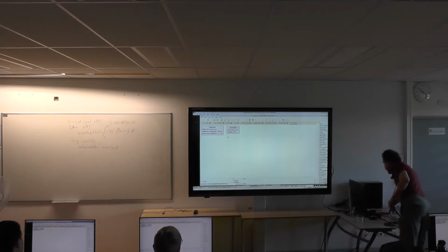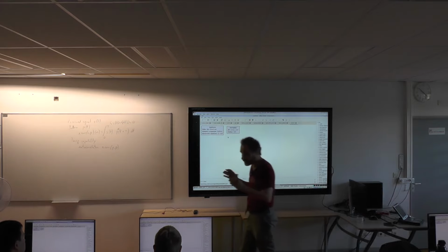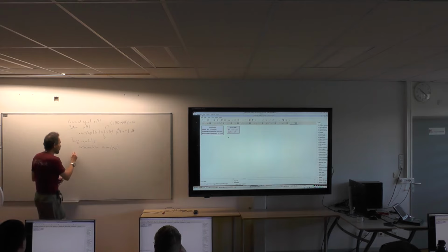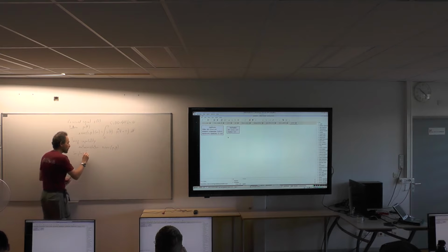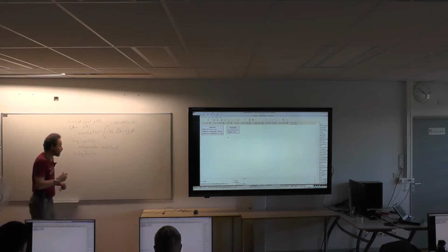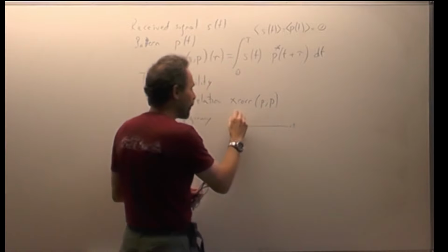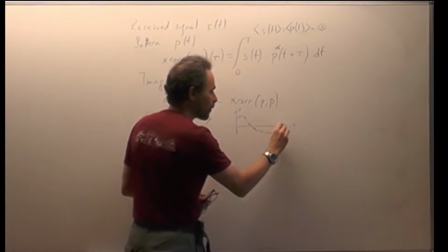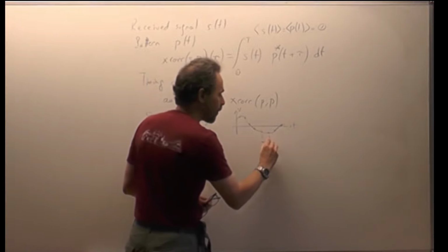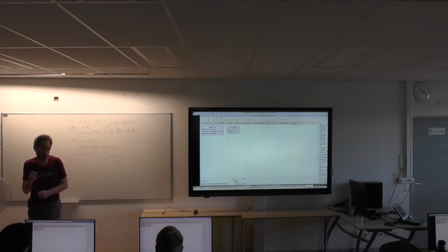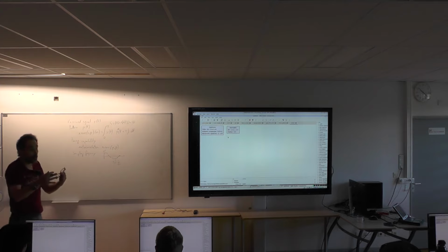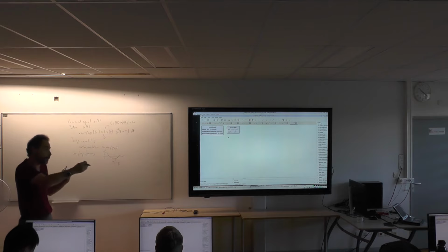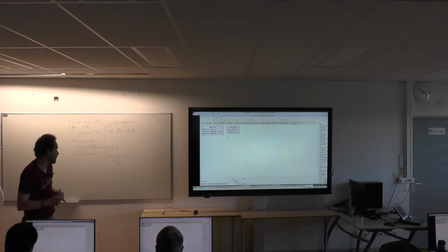Whenever you're doing discrete time signal processing, there is one quantity that will determine all x-axes of your charts, and that's the sampling frequency. In the time domain, when you have your continuous voltage, the sampling frequency determines the time steps when you sample the data. So these time steps Ts are the inverse of the sampling frequency. Whenever you have your samples, assuming you have not lost the continuous stream of data, you can identify the timestamp of each sample just knowing its index in the sequence.